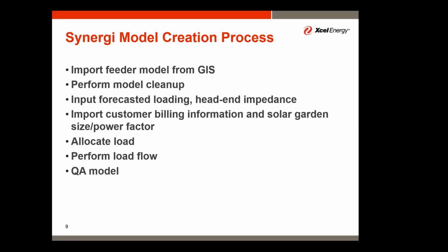Feeder accuracy checks and quality assurance are also incorporated in the cleanup step. Next, the forecasted loading and head-end impedance are added to the head portion of the feeder. Several other inputs are entered based on our data, as well as customer loads and metering information. And lastly, solar garden size and power factor.